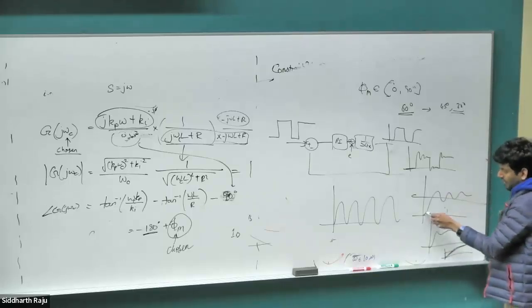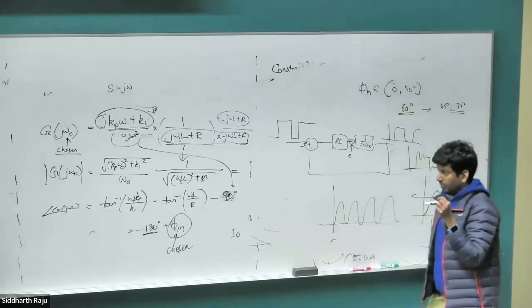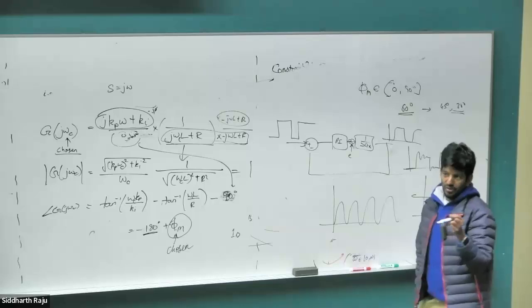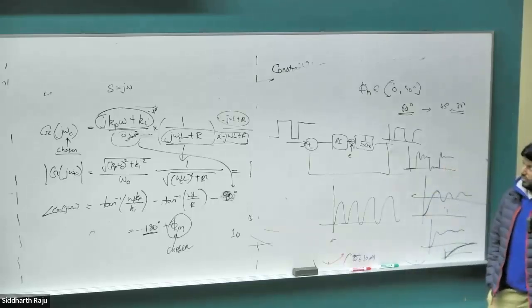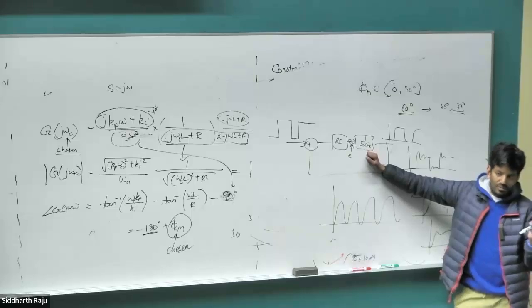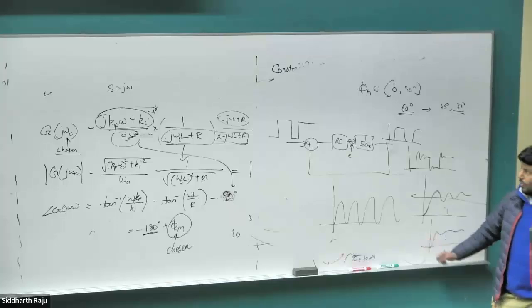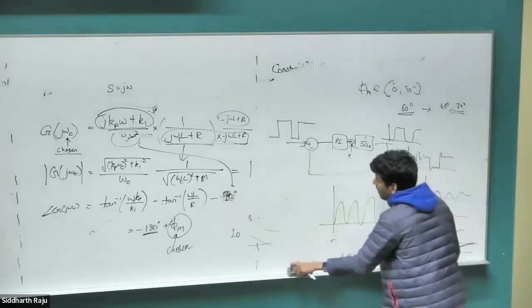It's going to have a very lagged response. If you want to have a very fast response, you would make your phase margin very small. But then there comes a problem that even slight changes in the parameters could destabilize your system. So if you want a fast response, you better have a good estimate of your model as well. If you have a very bad estimate, you have to settle for a much slower response so that your system can remain stable for a wide operating range. Right?